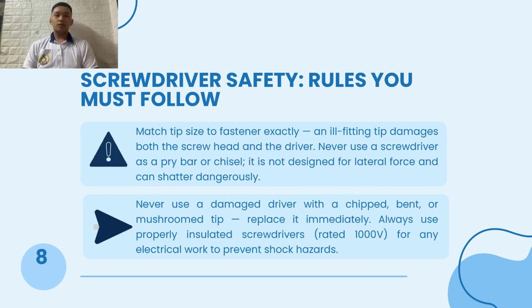Safety is paramount when using screwdrivers. Always match a tip size exactly to the fastener because an ill-fitting tip damages both the screw head and the driver. Never use a screwdriver as a pry bar or chisel as it is not designed for lateral force and can shatter dangerously. Always inspect your tools and replace any with chipped, bent, or mushroomed tips immediately. And always use properly insulated screwdrivers rated 1000 volts for any electrical work to prevent shock hazard.